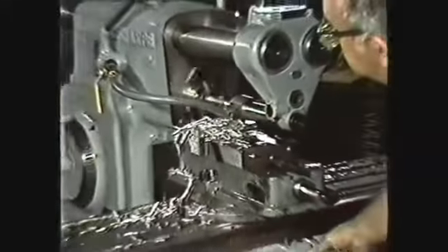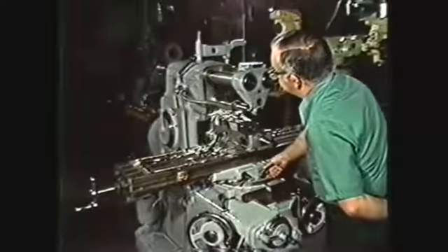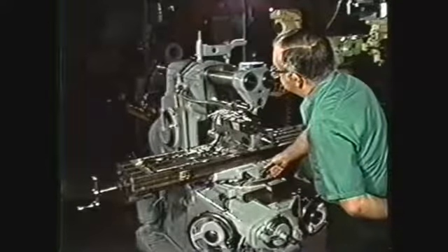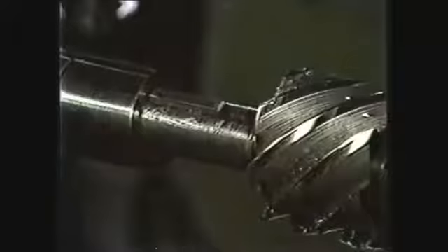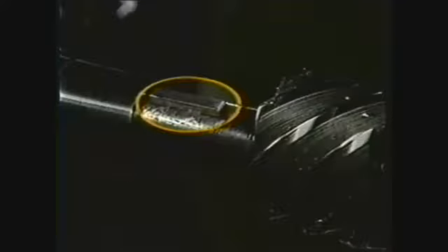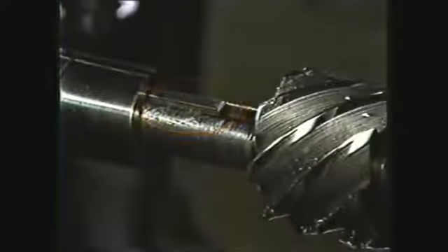This videotape will show you how plane and side milling cutters are used on the horizontal milling machine. In the machine trades, plane and side milling cutters are known as arbor milling cutters. This means that they are driven by a key which connects them to the arbor.